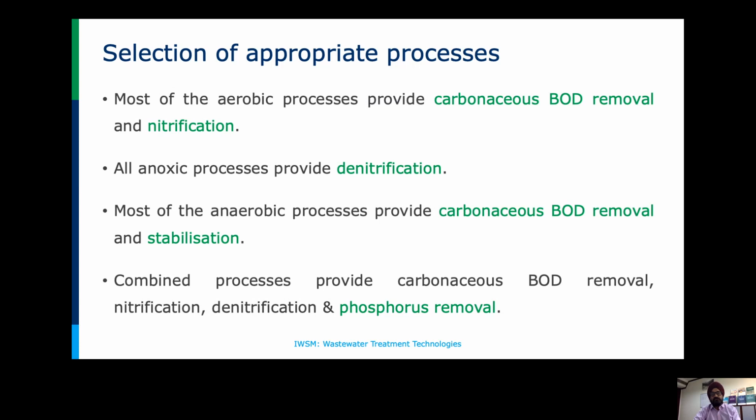And then we have the combined processes, which is a combination of aerobic and anaerobic. So since it's a combination, it does everything. It does BOD removal, it does nitrification and denitrification, and also phosphorus removal. So therefore, the combined process is like the gold standard or epitome of DEWATS. And you will see the DEWATS process is like a combined process, which will be explained soon.